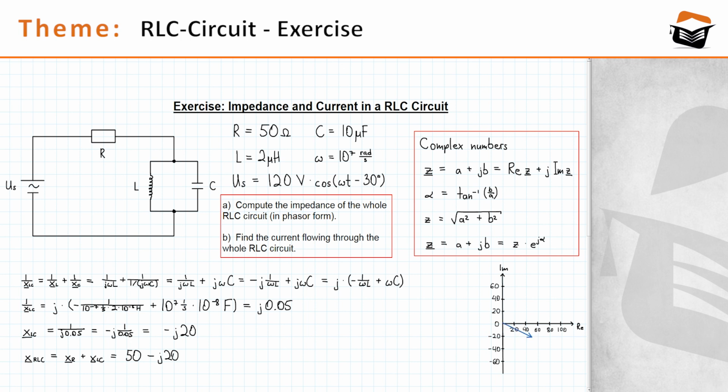And we also have the phase angle, which we will call theta. We'll just squeeze it in between the numbers. And the phase angle theta, which we will compute just in a few seconds. Actually, let's compute the angle and also the absolute value of the impedance. I'm saying absolute value because what we've computed here is not the actual value of the impedance, that's just a complex expression. To calculate the absolute value of the impedance, and hereby the impedance itself, you need to apply Pythagoras' theorem.